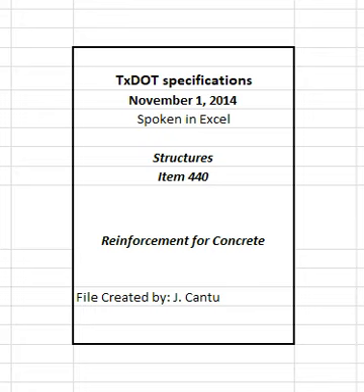Remove any thermal oxidation using pickling paste. Do not field bend stainless steel reinforcing without approval. Use 16-gauge fully annealed stainless steel tie wire conforming to the material properties listed in section 440.2.10, stainless reinforcing steel. Support all stainless reinforcing steel on solid plastic, stainless steel, or epoxy-coated steel chairs. Do not use uncoated carbon steel chairs in contact with stainless reinforcing steel.